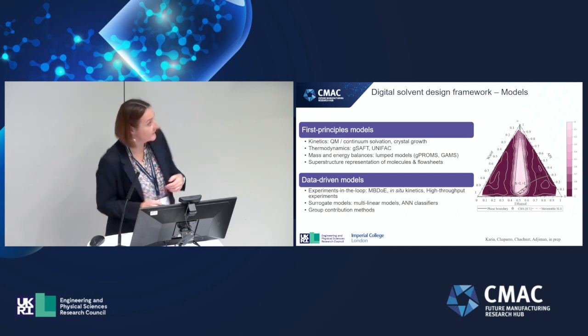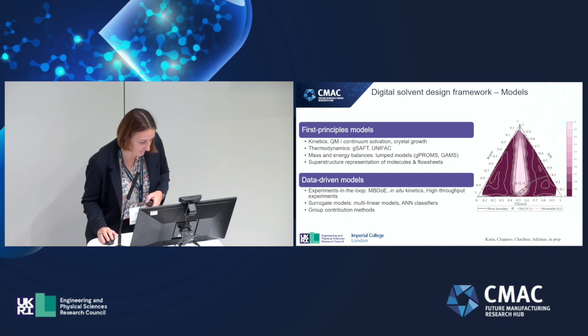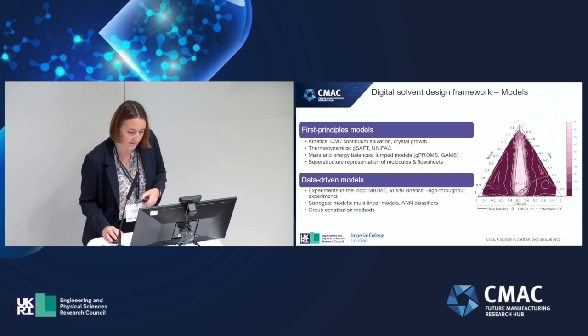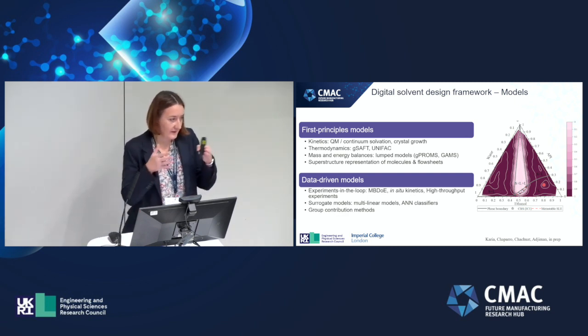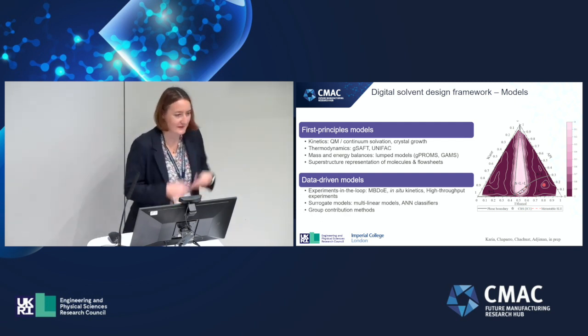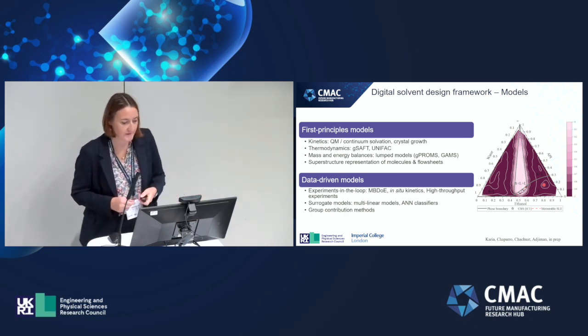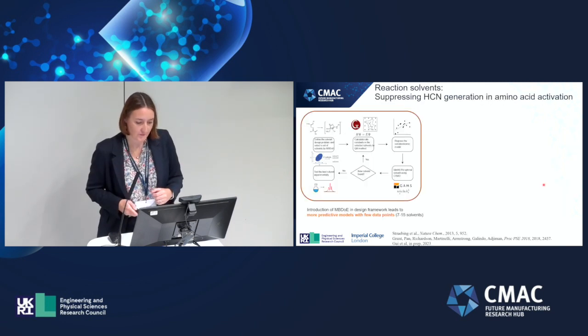So here, what you have in the middle is an area where we have liquid-liquid equilibrium, and we even have a solid-liquid equilibrium, and so that's light-colored. And then in those areas we have either solid liquid or purely liquid phase present. And so we can either avoid liquid-liquid if we're in a crystallizer, or we can design for liquid-liquid extraction, for example, if we want to. So we can put these as constraints, and it's very cheap to evaluate this model within the optimization framework.